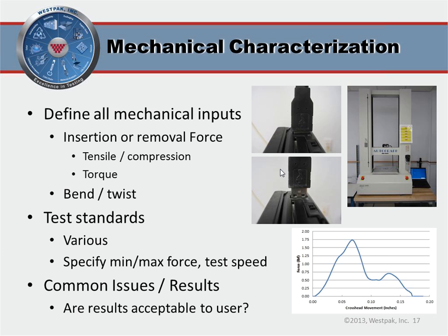The next slide, and this goes hand in hand, is what we call mechanical characterization. So if you think about how the product will be used, what's unique about your product, like your laptop, you can do quantitative characterization of most of the mechanical things. So for our laptop, I have an example here. We have a load frame on the right-hand side, and I fixtured a USB cord to a jaw and pulled it out of the laptop.